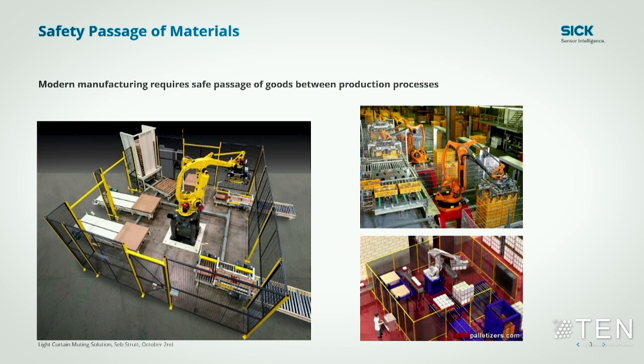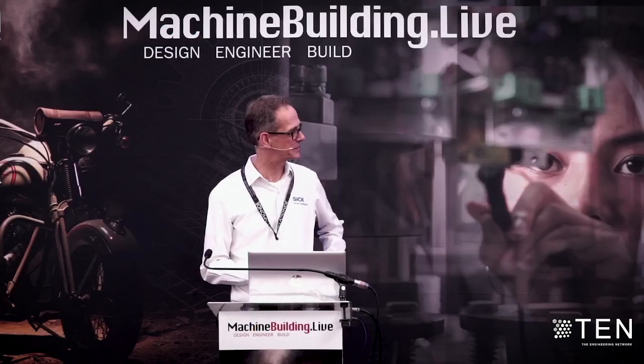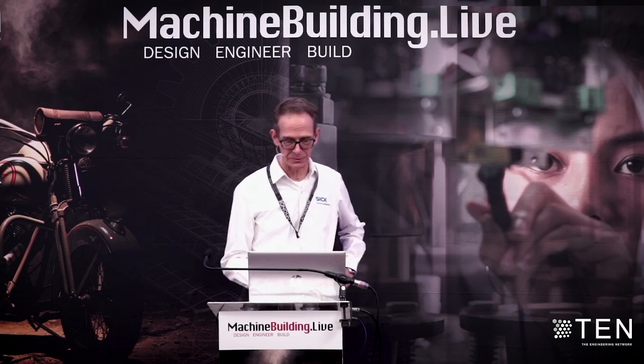Here we have an application which requires finished pallets or pallets to be depalletized, entering into a robot cell. And those points of entry that you can see around the cell obviously afford access to people. This is not an ideal situation because the robot is a hazardous piece of machinery, and we need to protect people from that situation.